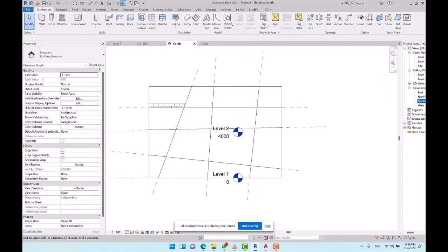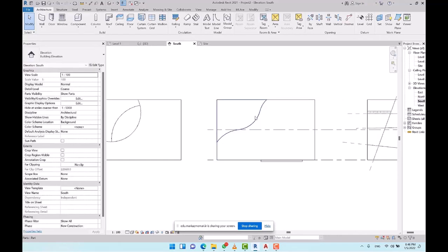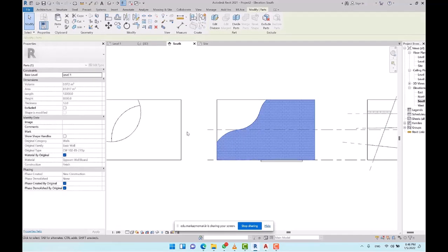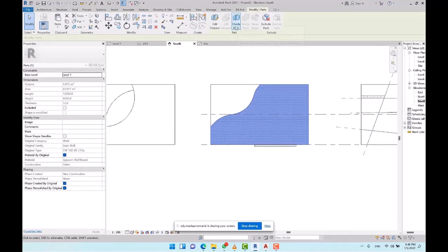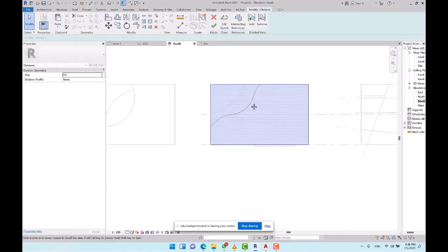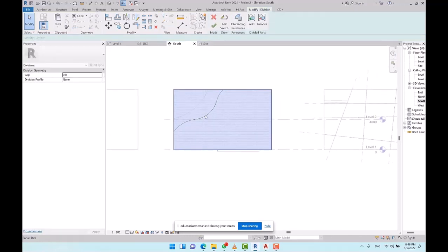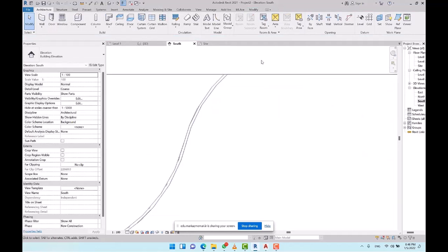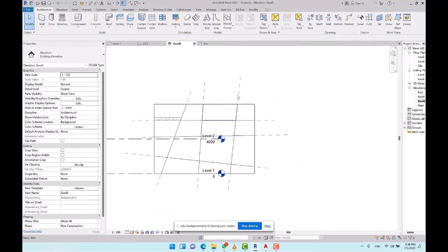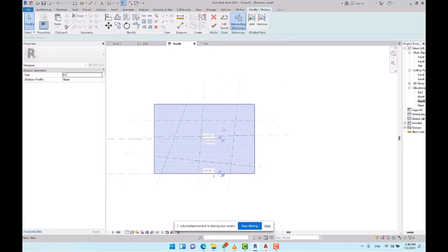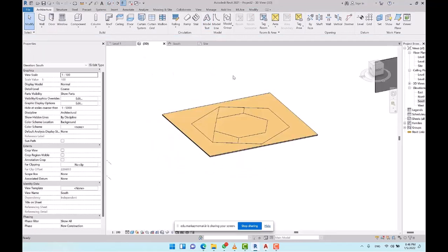Let's see. I open the shelf plan view, and in this wall, for example, let me edit this sketch. And then right now in the edit sketch command, here we have an option named gap, for instance 5 centimeters. If I click on finish, there's a 5 centimeter gap between the two divided parts. Let me check another geometry model. Again in edit sketch, I define a 5 centimeter gap and then I click on finish. Actually, these are interesting options. It is better to know them.